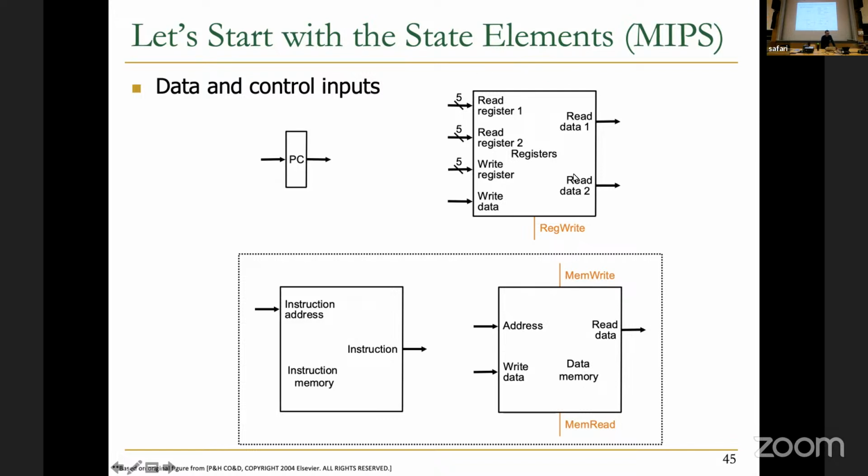And this is the register file. We have two register file ports for reads. You can see that there are 32 registers. And we have one port for write, and then the write data over here. So you can use two different IDs or the same ID to read two different registers or the same register, let's say, from two different ports over here. And you can use the write data as well as the write register ID to write data to one register. So this is all combinational also. You can do it all at the same time in a single clock cycle. Makes sense, right? And you know how to design these things right now.